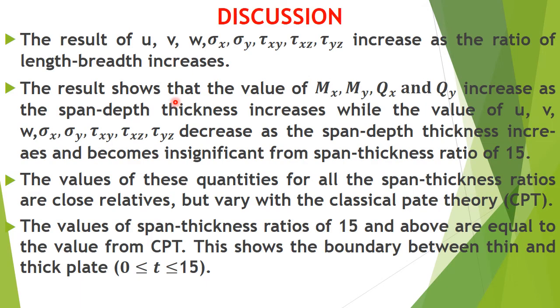So to infer in our discussion, we discovered that the results of the in-plane displacement, the out-of-plane displacement W, and the stresses increase as the ratio of length to breadth increases.